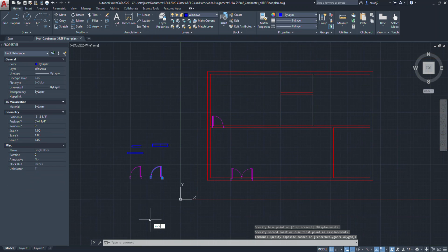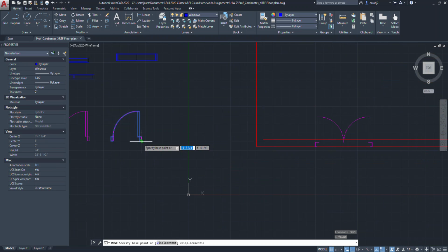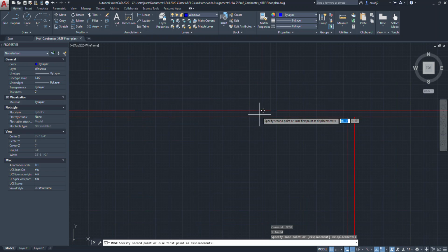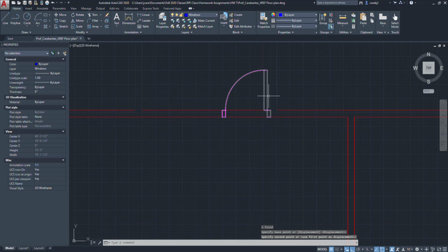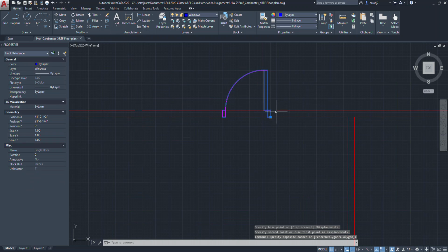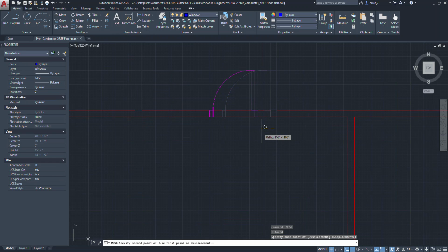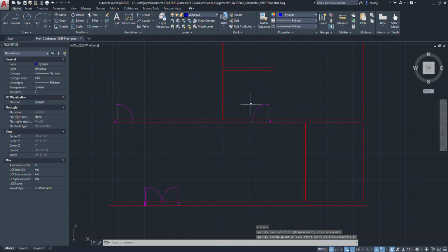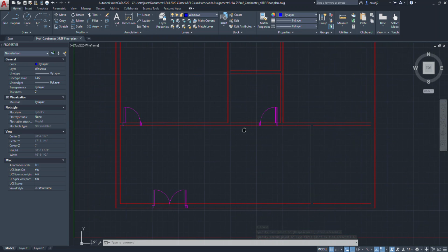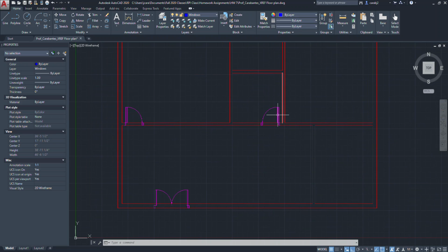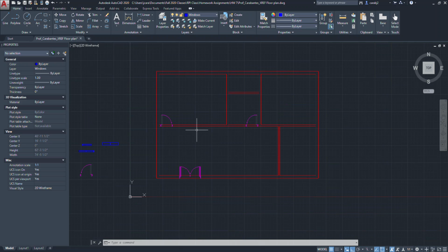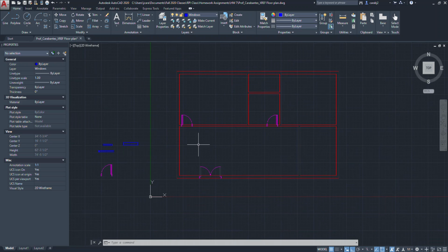I'm going to use this door for over here. Just make sure that your doors are not right up against the wall like this. Give it some inches. What you can do is give it maybe 6 inches off of the wall, or if you want it dead smack in the center, you can have it here. But typically doors are about 6 inches off the walls here, just for swing purposes and just so that there's a better flow for the room.